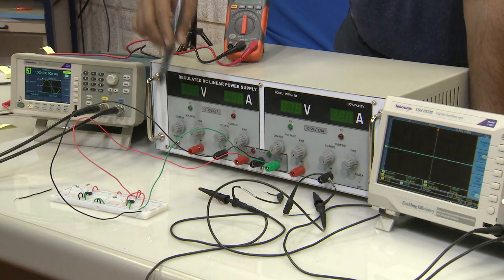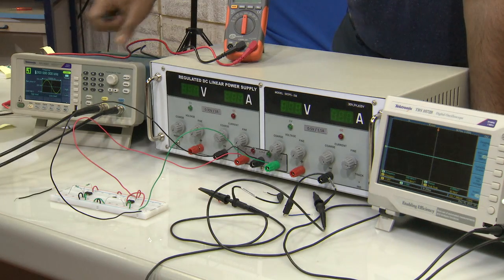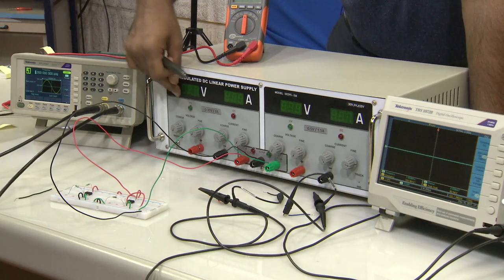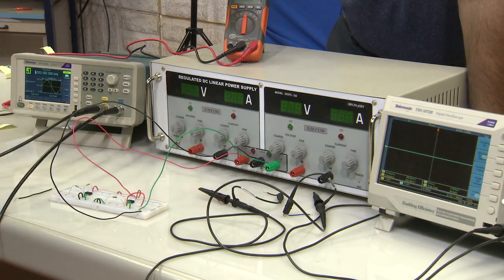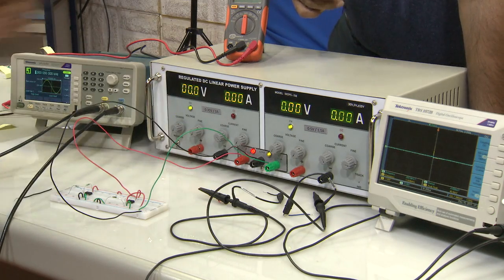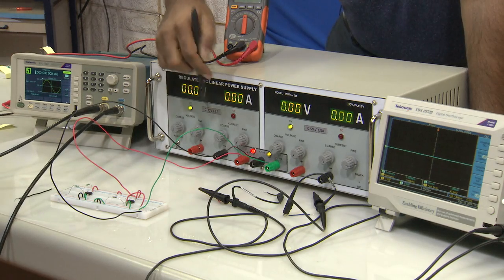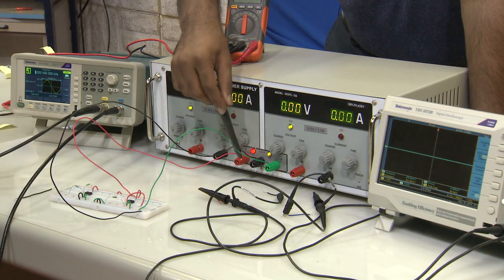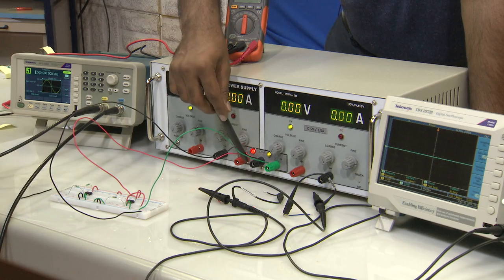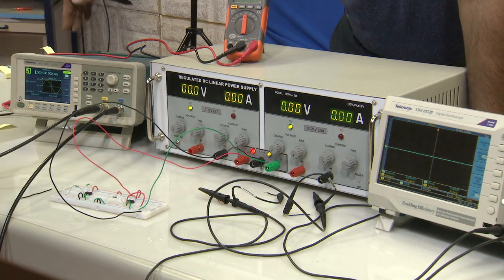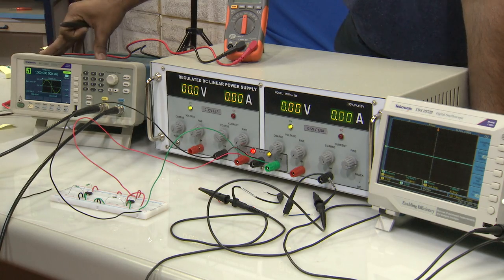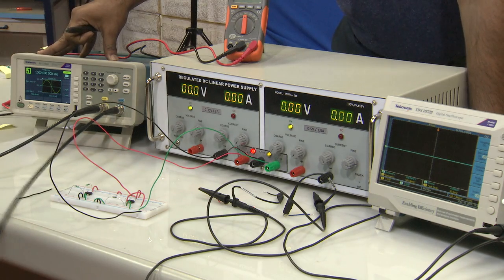Now, we will apply the input signal. Before that, we have to start the operational amplifier. So, we can now apply the power, yes, DC voltage, excellent. The DC voltage, again, is plus 15 and minus 15 on these three terminals: red, black, green. Now, we will apply the input signal from the frequency generator. So, what is the frequency generator input signal? Can we focus on the frequency generator please?